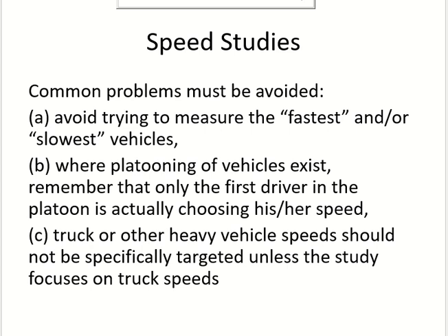So when you are doing manual counting, then you have to take care of the breaks. Okay. So we saw one example where there was a 3-minute break and there was a gap as well, alternate gap as well. Okay. So we saw how we can deal with these things. And then we moved on to speed studies. Okay. So speed studies can also be manual. You can do it using a speed gun or a speed radar, okay, or you can do it using a stopwatch. Now, if you are using a stopwatch, then we can have two types of errors in speed studies.